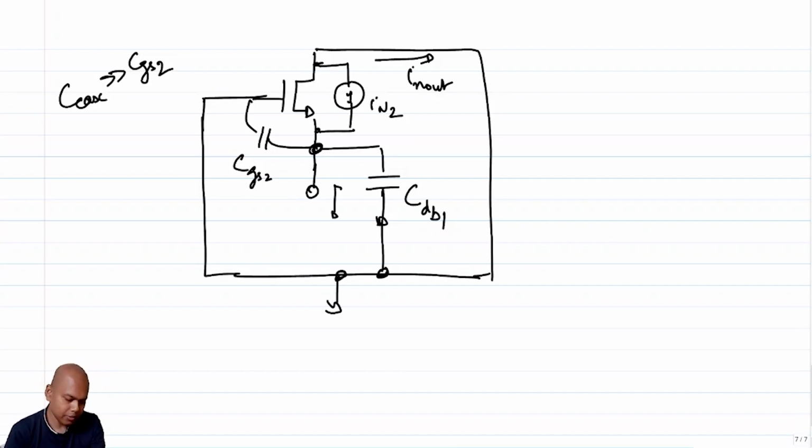So this is quite simple because at the source of this M2 transistor, the only thing you have to understand is that the amount of current that comes out of this terminal is the same amount of current that has to go in through this terminal. So if I can find out the amount of current coming out through this terminal, I am good. Correct? So let's see.